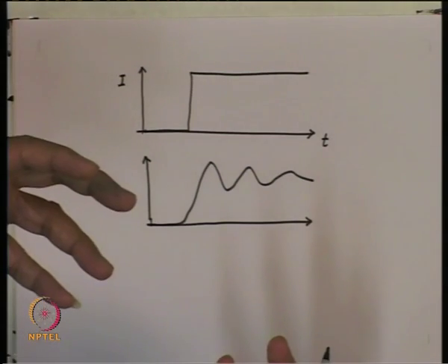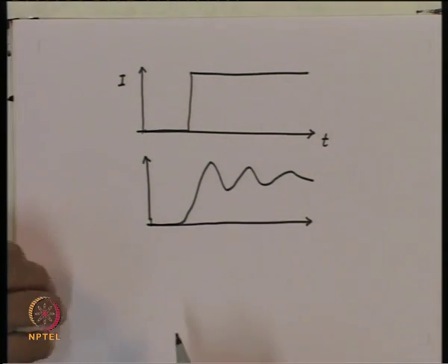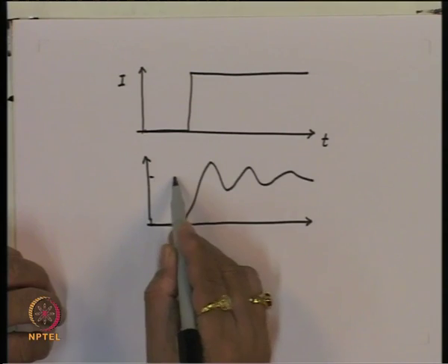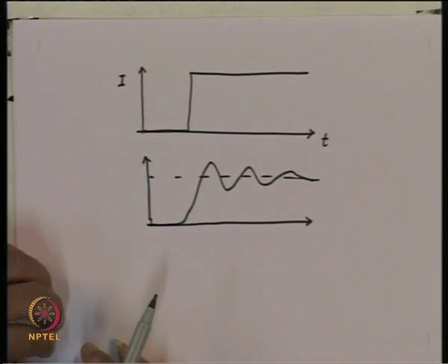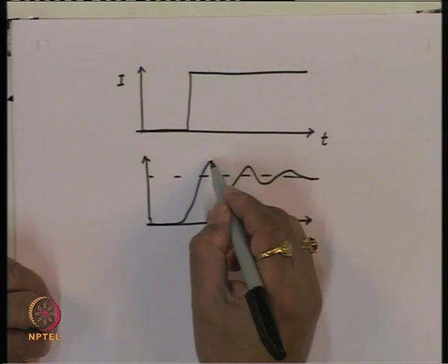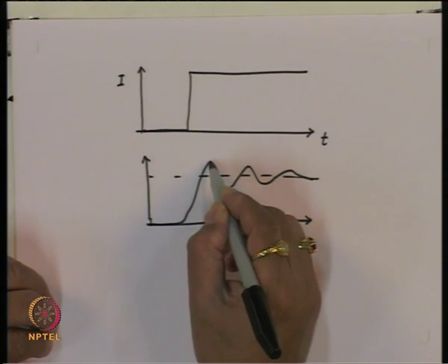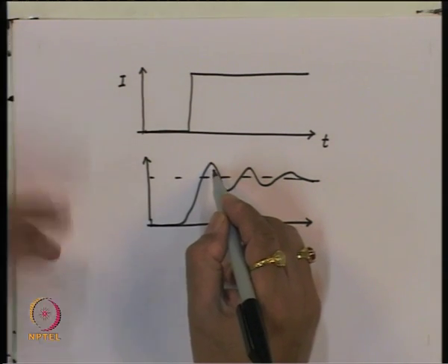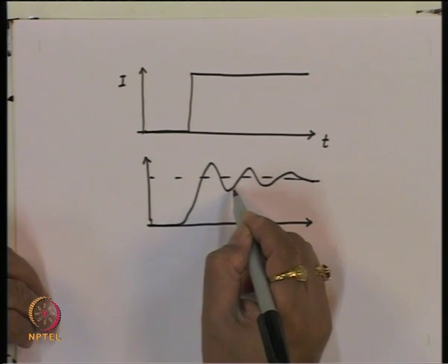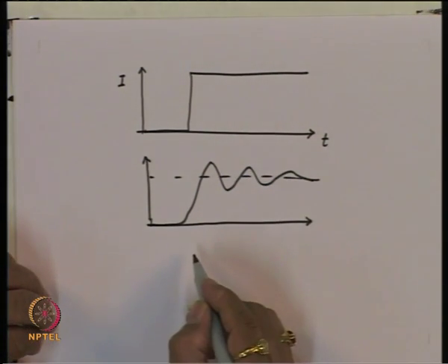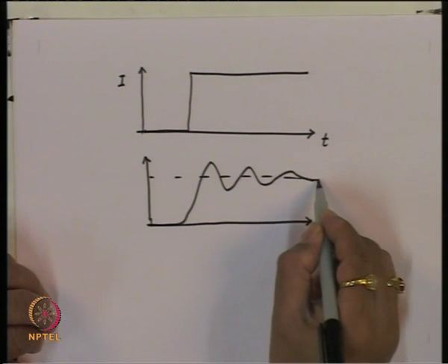So, again you will have electron hole pair accumulation and so on. So, you will see light more than what is expected in stable condition, then the gain decreases, the electron hole pairs will reduce, and again the gain will fall down. So, you will get some kind of oscillations like this, and after some time you will get the stable output.